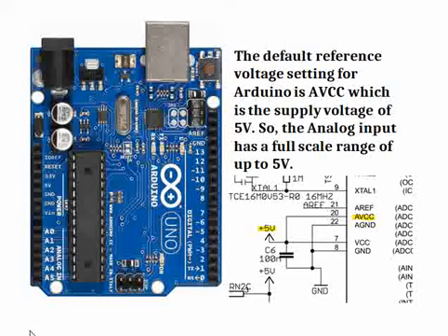One could be 1.1 volt, which is the internal reference. One could be AREF, which is a pin on the Arduino Uno where you can give an external supply to act as reference, or by default the VREF of Arduino is connected to AVCC as shown here.